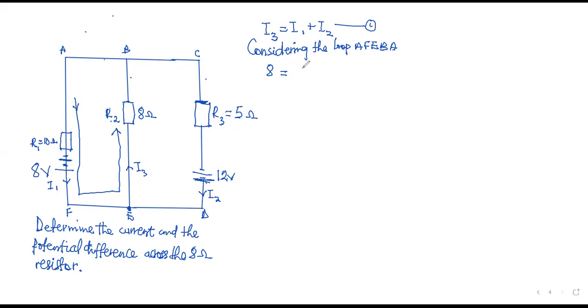What's your reason? I chose positive because if the direction of current flowing through the resistor follows the direction of your chosen loop, the PD across the resistor is positive. If the direction of current flowing through the resistor is against the direction of the chosen loop, the PD is negative. So would that be positive or negative?